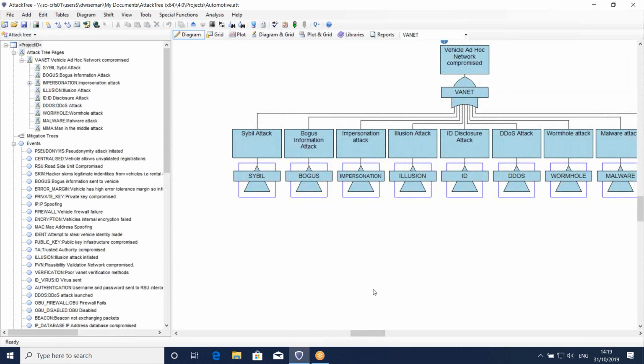So you want to know the frequency with which a certain hazard will occur, and you can build a logic tree that represents the combinations of different component faults, conditions, operator errors that might lead to that hazard. So, it could be pump failures or electronic component failures, or maybe an engineer makes a mistake during maintenance. And all these things come together to cause some kind of system hazard or failure.